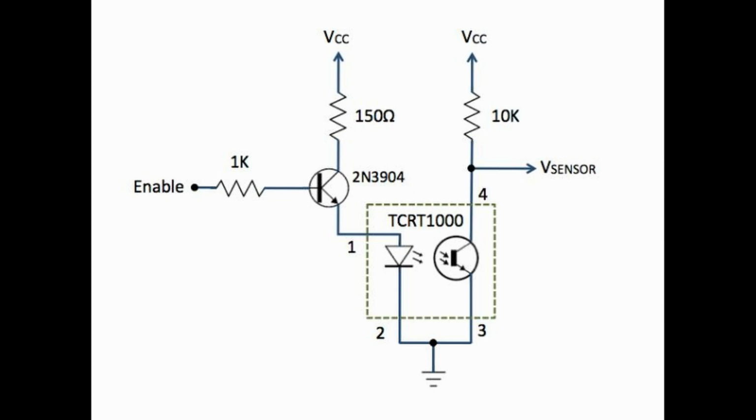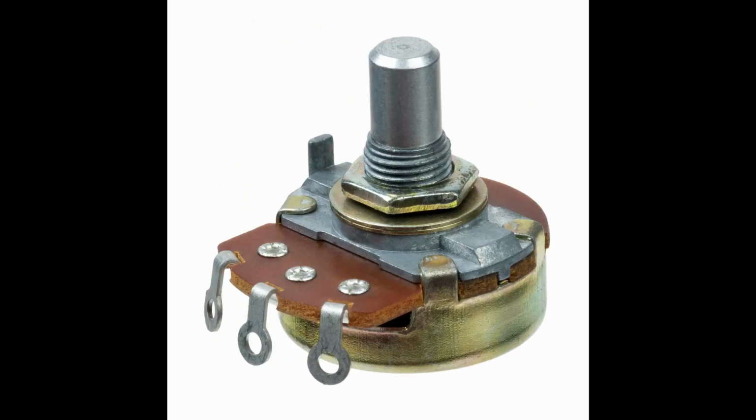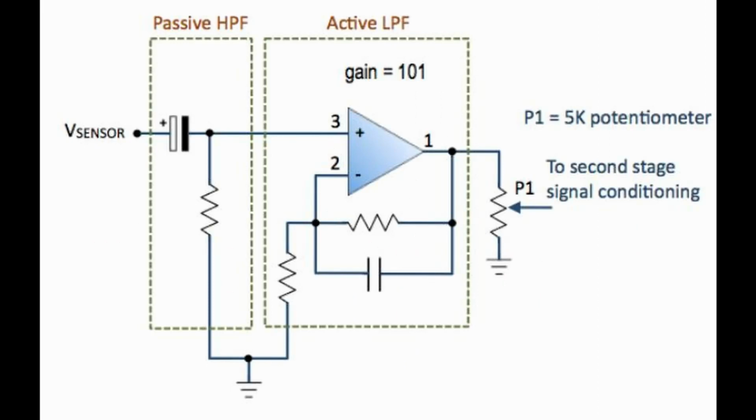The main circuit is actually quite simple, only having 5 components. But the output signal is unfortunately way too small and has way too much noise in it, so we have to add some additional components. We can use a capacitor to filter out the high frequencies of the signal, and then use an operational amplifier to boost the signal. And that parallel to a capacitor can be used to filter out the lower frequencies. Then we connect that to a potentiometer to be able to control the output signal, and then repeat the filtering and amplification process again. Then we finally have something that is readable.